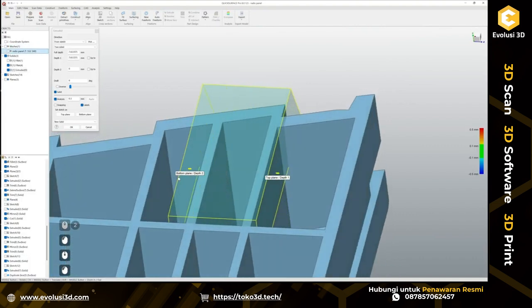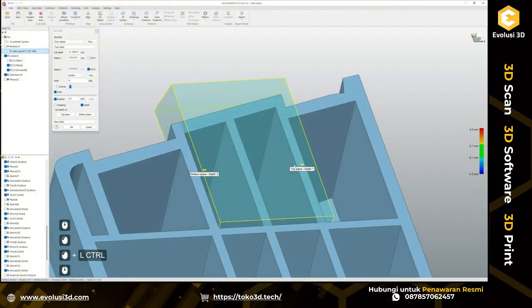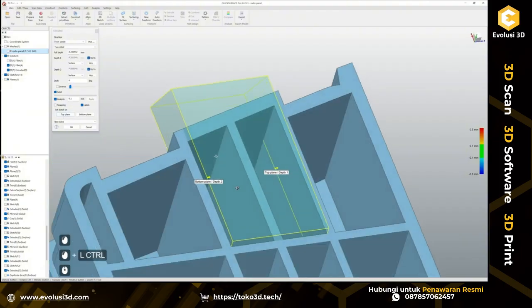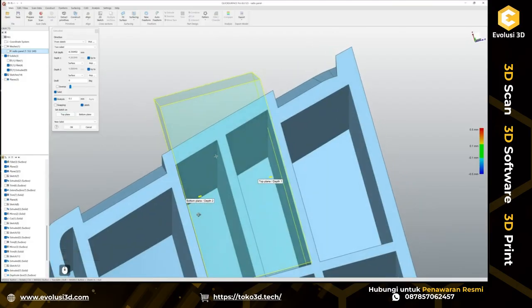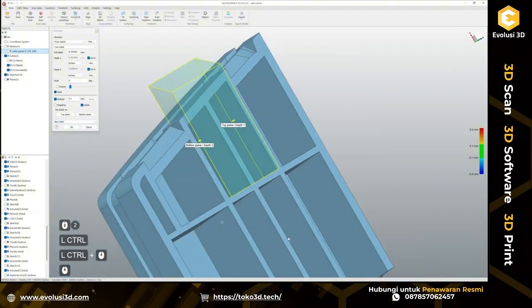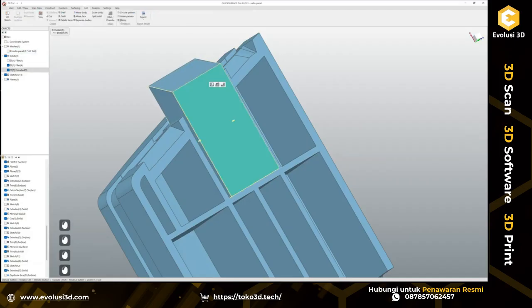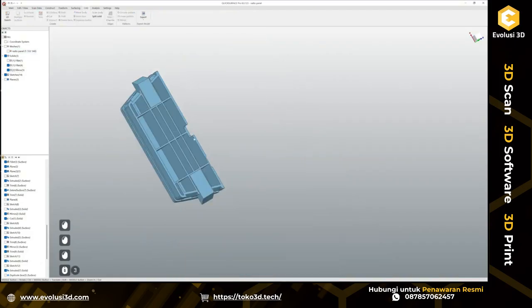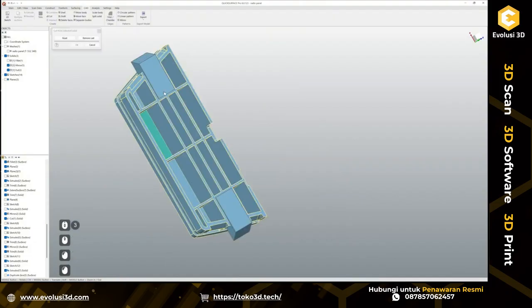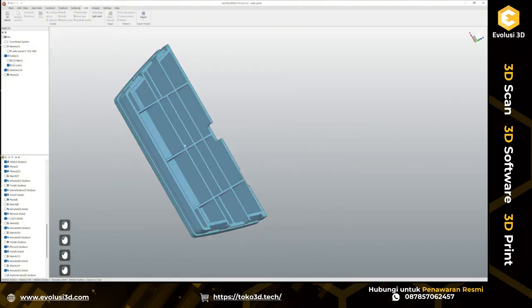And now I want to extrude this to this surface and up to this surface. Instead of doing cut right now, I'm going to accept this result, mirror to opposite sides, and cut those two away.